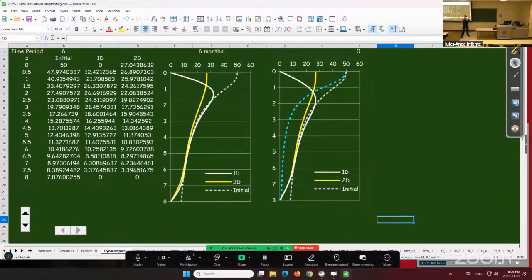But the strip footing, because it has contributions from so many points in the distance, infinity, so it takes longer to reduce. Because it has more length. So we're assuming that they add up because of linear elasticity, but they add up with depth, you know, you have the projection of the cone, of the bulb. And so they add up. So it makes sense. You would expect the strip footing to be larger at any depth. Okay. So right there, I'm happy with that initial distribution.